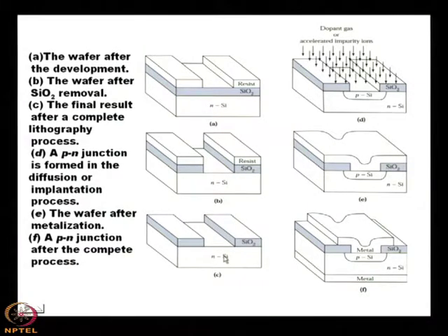Or if the hardened region is on the side portions, then it is gone now, in C. So, it depends on the nature of the photoresist. What is the significance of a hardened region? There is no significance except that it is a chemical property. For that particular type of hardening or softening, you will have to use different kinds of chemical etchants to etch it out.